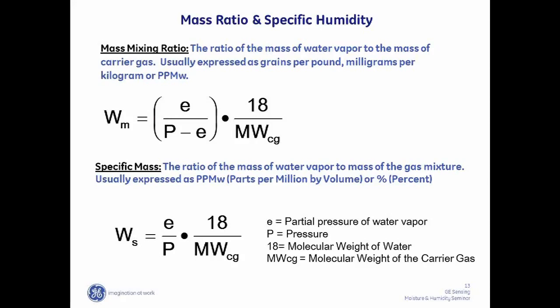One of the byproducts of combusting a fuel, if you take any fuel and burn it completely and efficiently, you get heat, carbon dioxide, and water. So by measuring the water coming out of the process, you can back calculate, or get an idea of, the efficiency of the engine. The term is called stoichiometry. So there's an example where the mass ratio would be used.